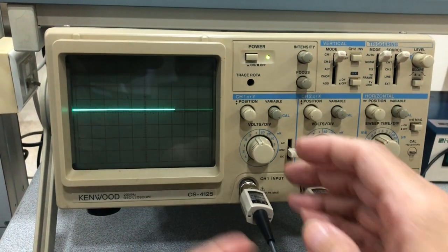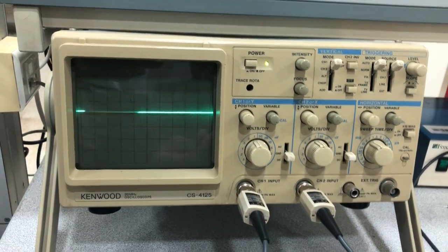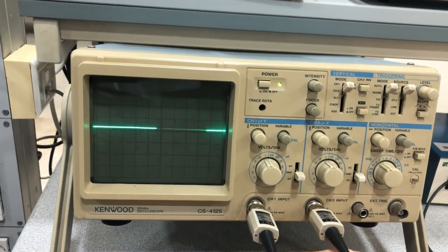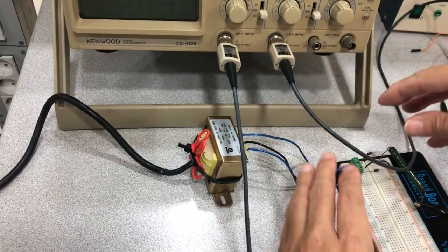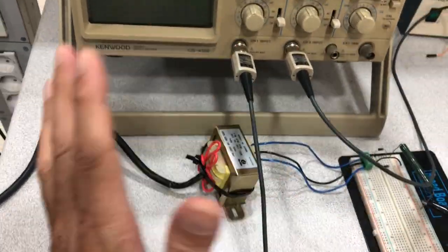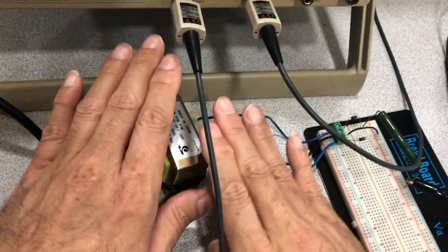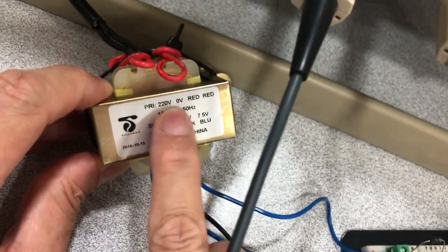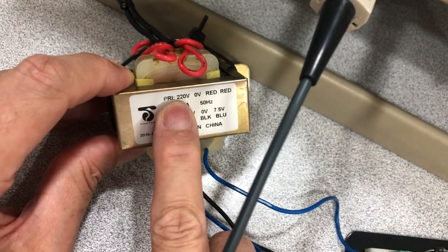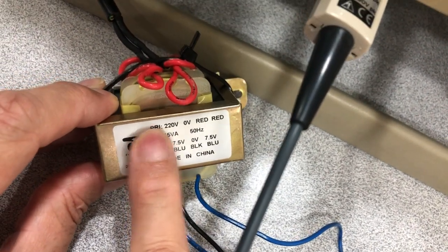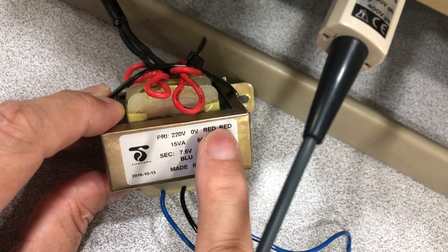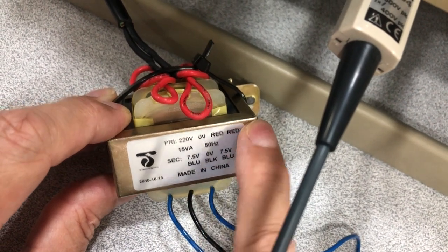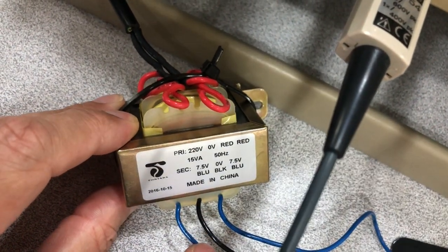The first thing you want to do is I'm dealing with a transformer that is going to put out, we learned in the simulation of this rectifier, around 10 volt. And we bought these transformers intentionally. Let's talk a little bit about this transformer. It has 0 in, 220 in, so they say primary is 220 and 0, and then you use 2 wires called red, the red and red coming out of the transformer.